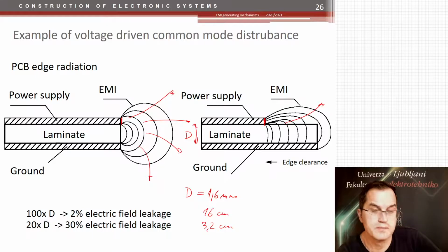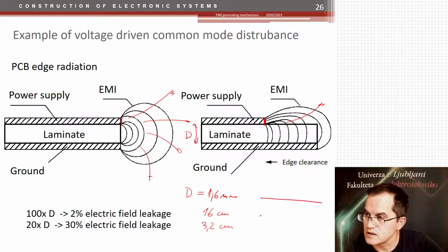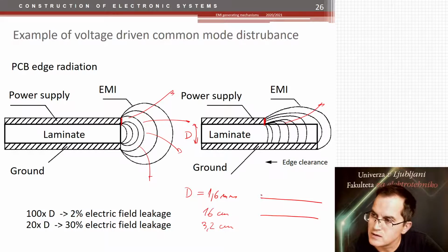But what can you do? Well, the other thing is to decrease the thickness. Decreasing the thickness would mean that your PCB now, maybe if it is a 4-layer, you can afford it. Having the mid part very wide and this very, very close together. And here you have ground.